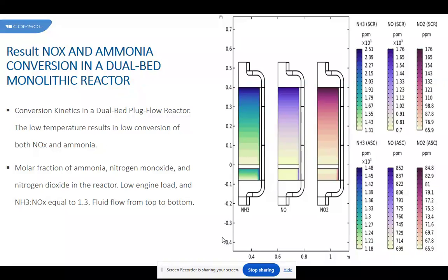Another idea that has been proposed is to use composite monoliths composed of rings of various cell densities to improve the light-off performance. The effect of such a design was briefly explored, and showed that combining 400 and 900 CPSI cell density substrates reduced the light-off performance compared to the use of single cell density.